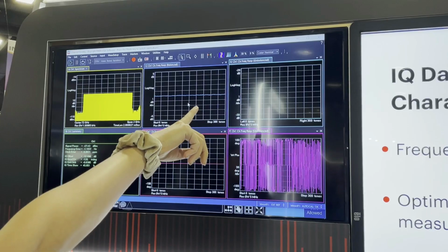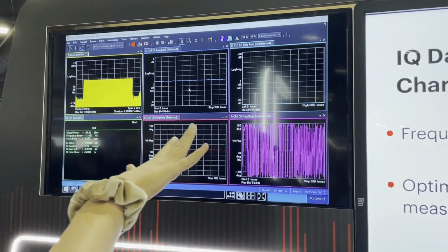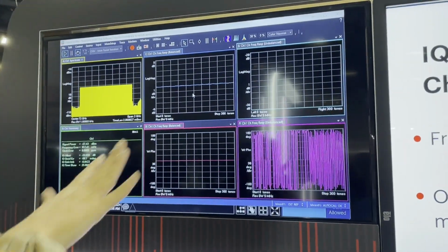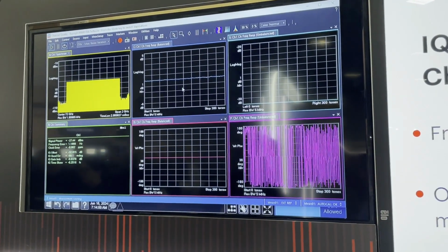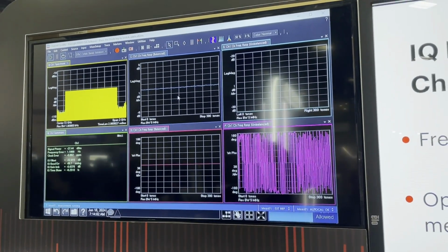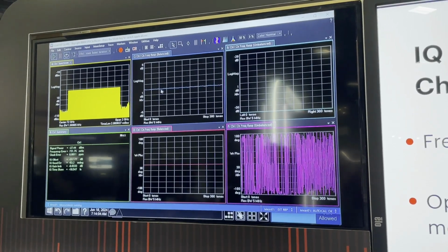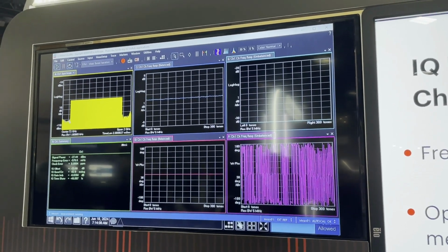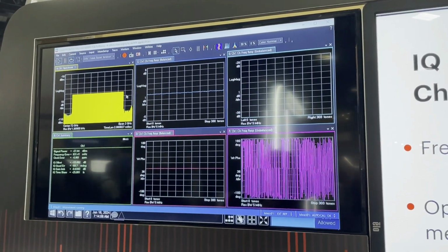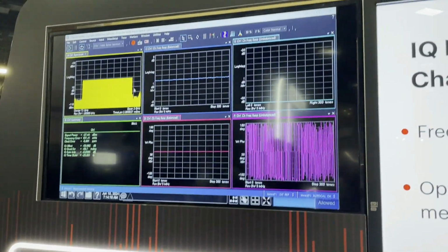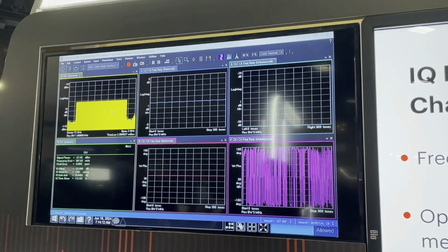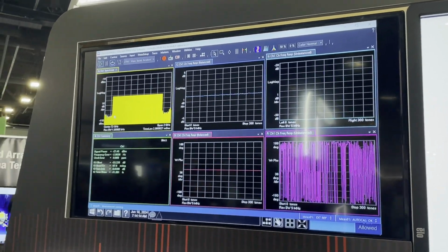As you can see, our unbalanced tones are completely eliminated. They're reduced down to the noise floor. You can't even see them anymore in the scaling that we're using in VSA. The balanced tones are completely equalized. We can see that our calibration comb has a completely flattened balanced tone response and virtually no images. We get about 40 dB of dynamic range.